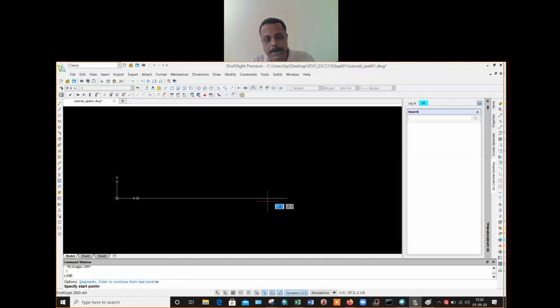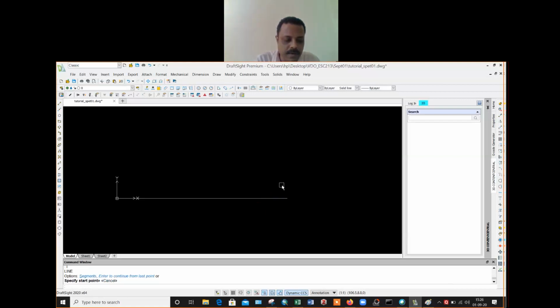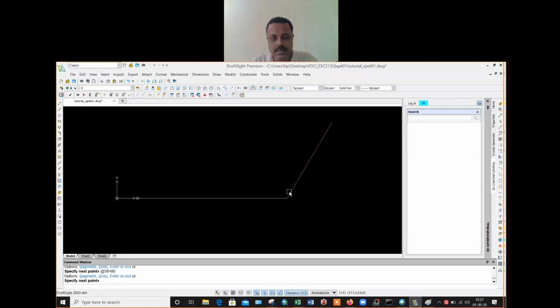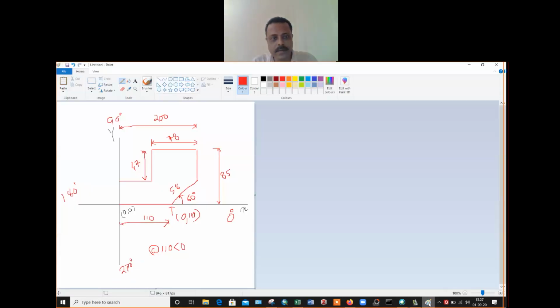But if I press F3, I can select that point. You see, I can pick up this point. So from there, what is my next point? @58<60 degree.